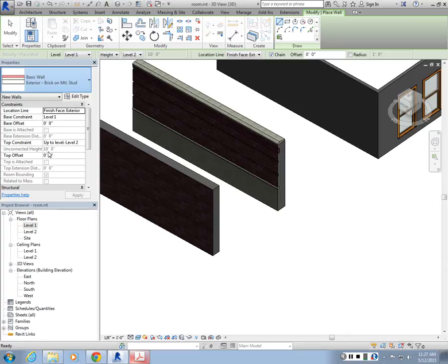It does it in this project, I think. Okay. It's a good question. The other thing is, if you're creating custom objects, you're creating them as a library object, and if you open a new file, you can also bring them into it, right? So if I create this custom wall, I can import it to the next project I want to work on, and then keep using it.